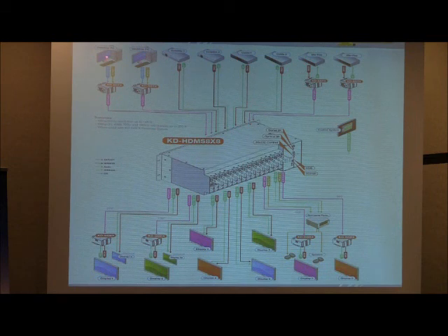You may have input devices that are far away, not at the point where the matrix is mounted. Let's say it's a laptop or desktop computer far away. In that case, the user will have a transmitting balun that will convert HDMI into Cat5 and connect it to the input card. Or if you have local devices like cable and satellite boxes that are remotely controlled, these can be mounted together and connected through an HDMI cable. This kind of installation is an example of how the whole system can be integrated through one matrix switcher over a variety of distances for a variety of applications. And this is actually demanded by the user.